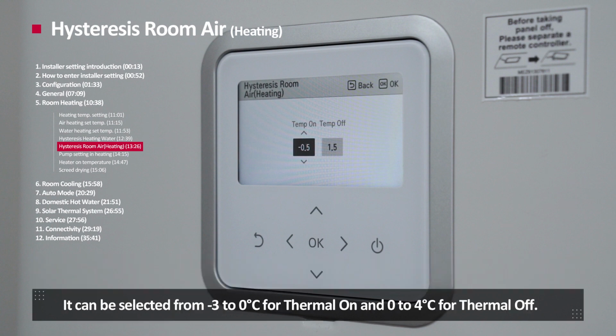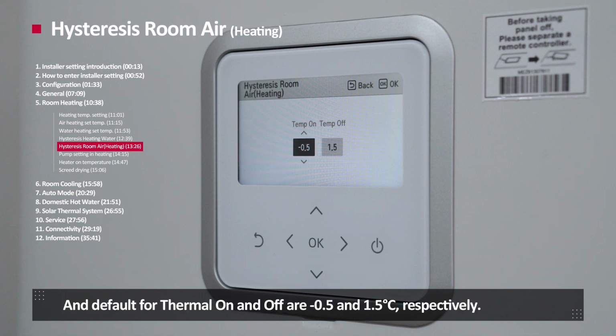It can be set from -3 to 0 degrees Celsius for thermal on, and 0 to 4 degrees Celsius for thermal off. And default for thermal on and off are -0.5 and 1.5 degrees Celsius respectively.